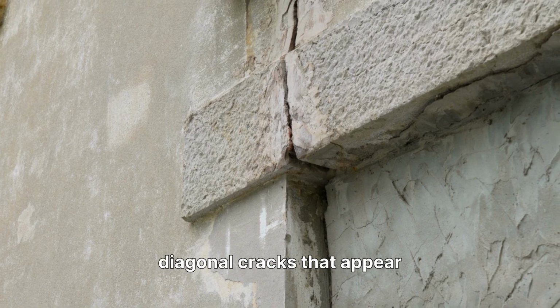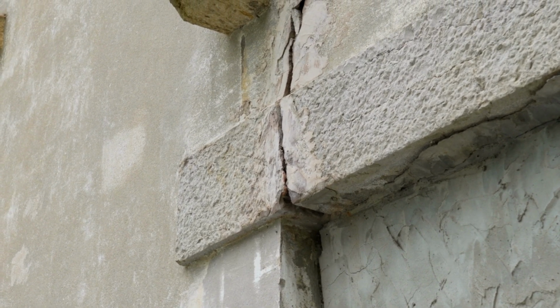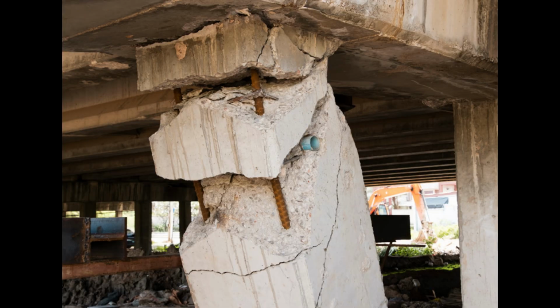Those diagonal cracks that appear near the supports of reinforced concrete beams, that's shear at work, trying to tear the beam apart. To stop that, we use stirrups, vertical steel bars that tie those cracks together and keep the structure from failing suddenly. Because shear failure is brittle, it doesn't give you much warning. Everything seems fine until it's not.